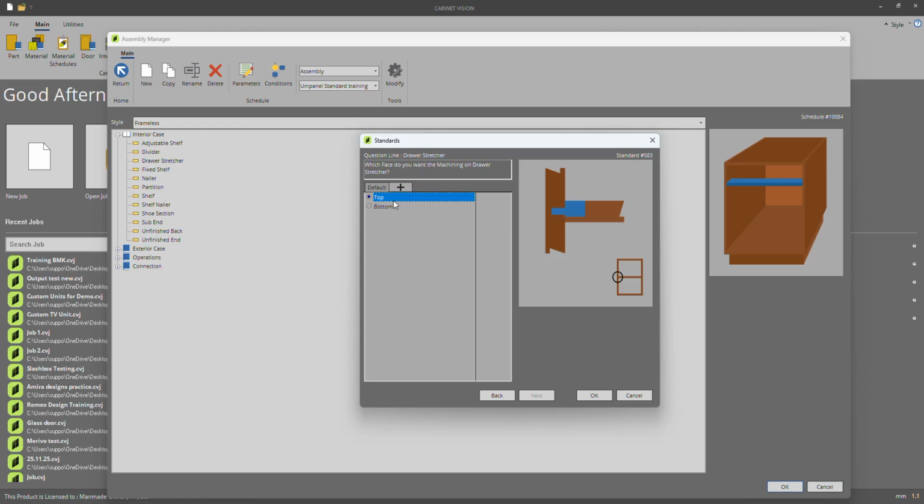Now, sometimes you can use that when you're busy with the oven unit, where the cam connectors are seen in the open space from underneath, but if you're doing a shelf, you don't see it from the top, you see it from underneath. The nice thing also is you can set this as a standard that most of your units use, but if you do have that one specific unit that needs it to flip, you can flip it on just that unit itself. And then we can't say next anymore, so we can say okay.